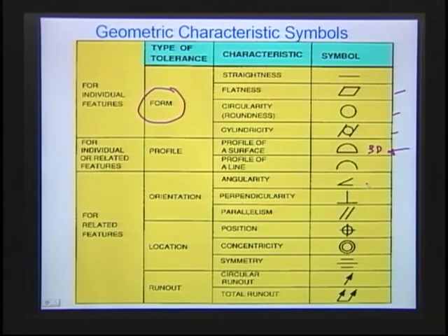We're going to use a lot of the orientation tolerances. These are our orientation tolerances. Let me circle this one here because I want to make sure you understand that. That's profile. That's our big kahuna there. And then there are orientation tolerances we're going to talk about. In the orientation tolerances, we're going to use perpendicularity. We're going to use parallelism, and I think there's an angularity or two in there. The angularity, all of these tolerances, they're really the same, right? If you really take a look at them, they're all really the same type of tolerance. It's just controlling the orientation of a surface. The angularity is used for something other than 90 and 180. Perpendicularity is 90 degrees. Parallelism is everything that's parallel or 180 degrees.